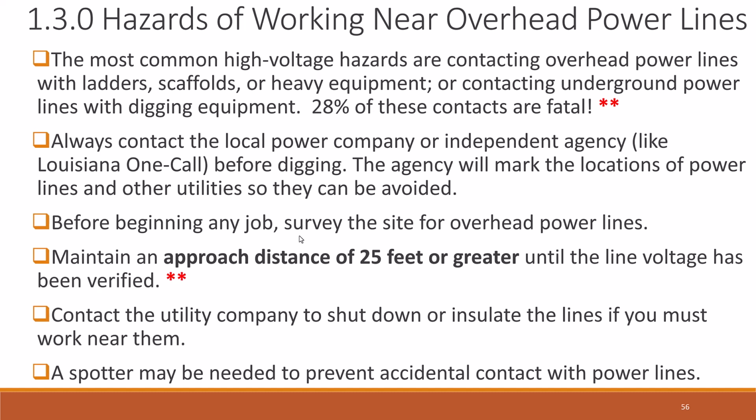You always contact a local power company or independent agency like Louisiana One Call before you dig. It's a free service. It's not free if you don't call them. In other words, if you don't call them and you dig up something, then you have nobody else to blame but yourself, and you'll be paying for that damage to the services underground.